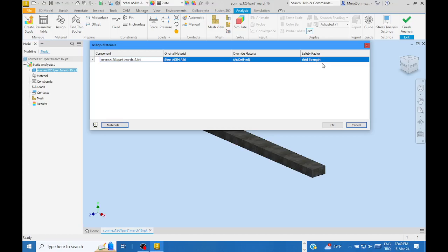Say that the object cannot be used under the action of such a load, so decrease the load. The elevator is not suitable for 10 people, but say maximum 8 people can use it. So the factor of safety is going to be calculated relative to the yield limit, not the tensile limit.